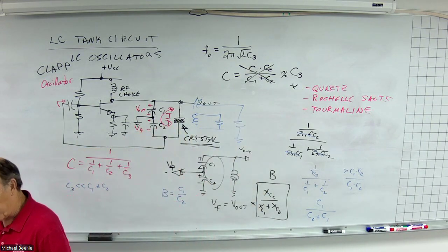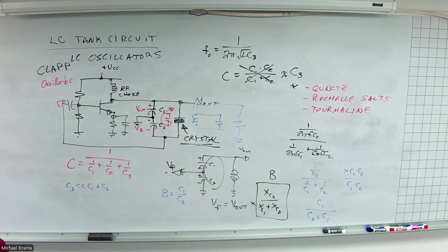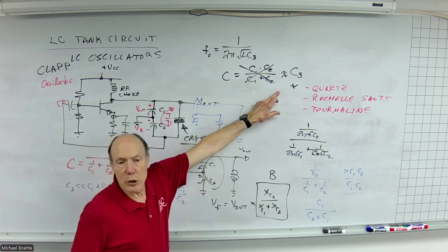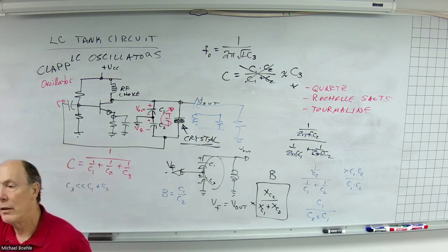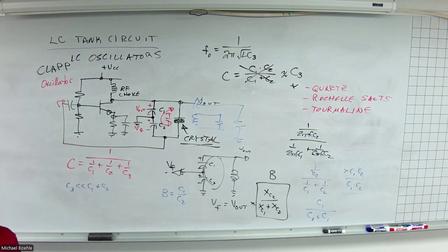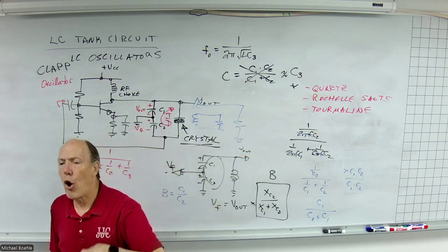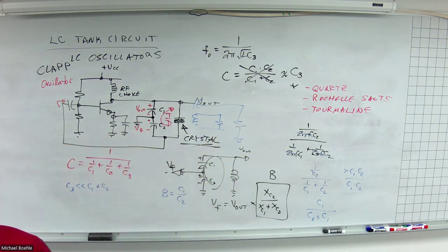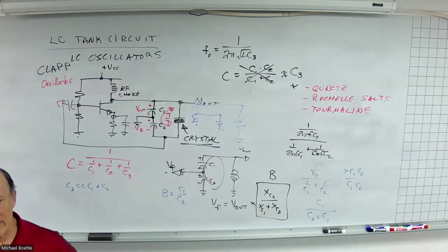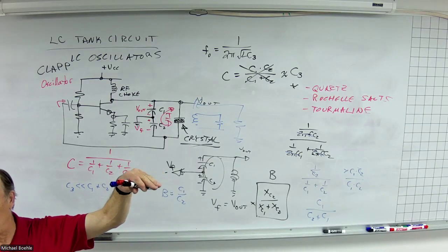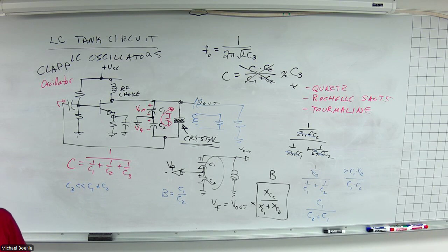Quartz provides a good frequency range. The thinner the material, the higher the frequency. So you get limits to how thin the quartz can be, which limits your upper frequency. Tourmaline can be cut thinner and still work. So that's how you get your really high frequency crystals. Rochelle salts have a relatively low electrical output, so not as good. They can be used for other things. The quartz by far kind of falls right in the middle of that. Fairly high electrical output, fairly high frequency range. Typically.